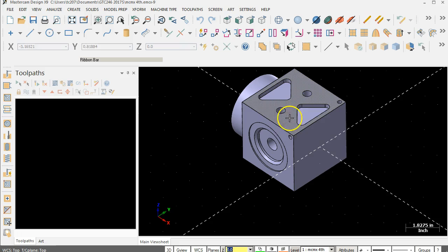I should be able to take an indicator across this face, mount this to the rotary, take an indicator across the face, get this level within at least a thou or two at the worst, probably within a couple of tenths if I adjust for the rotation, and then knowing what the size of the block is, touch off, subtract some amount, and that becomes my 0, 0.